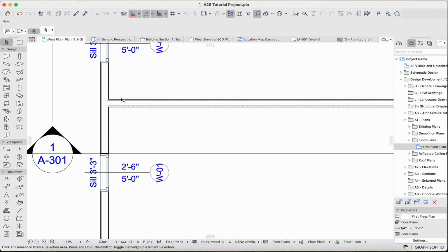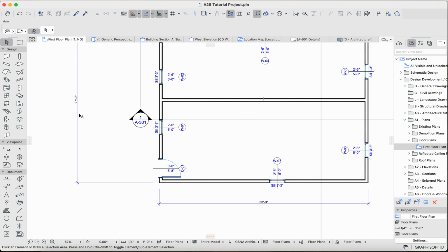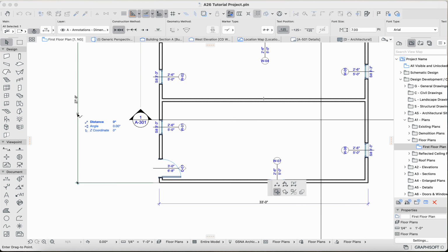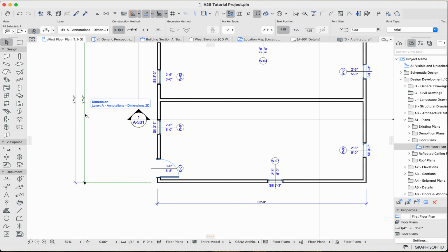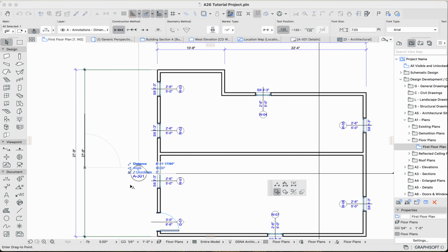However, to use that convention that we discussed earlier, I'm going to demonstrate something really quickly again. I'm going to hit Command Option D to duplicate this dimension and drag where I want that to be. Then I'm going to split this into two dimensions: one for this side, the living area and the kitchen, and one for this side, which is where we'll probably have the bedrooms.